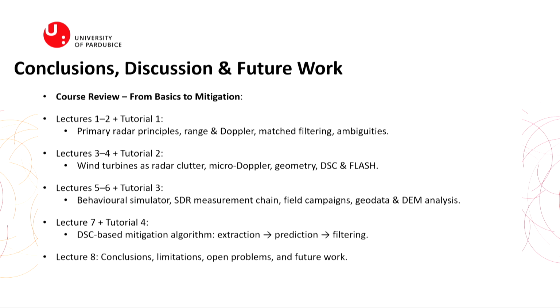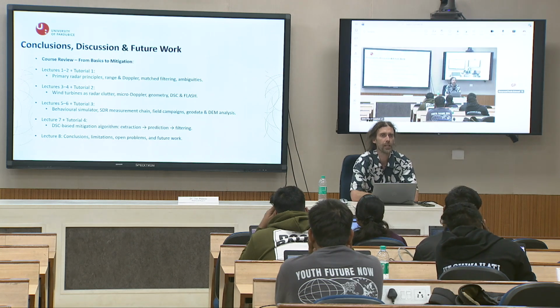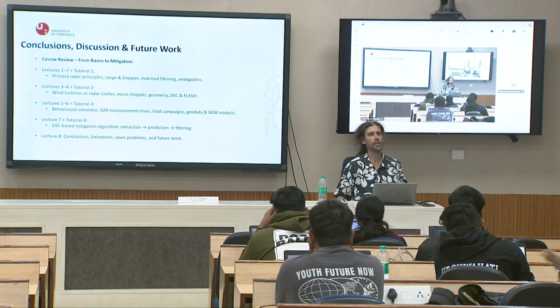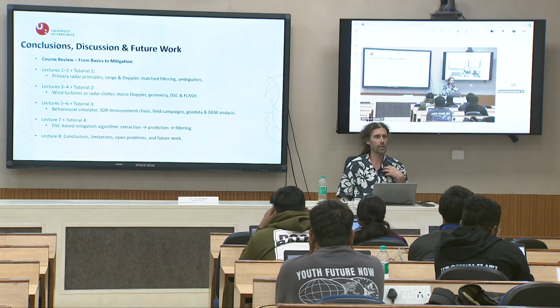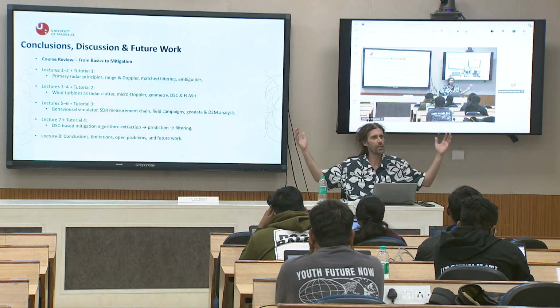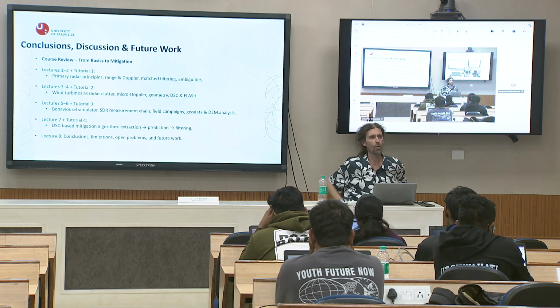So we designed, you already know how to design the measurement chain, what you require in principle. I showed you our own solution because we have this equipment. If you have other equipment, it will be tweaking of some parameters, some setting of different carrier frequency, bandwidth, sampling rates, and so on.